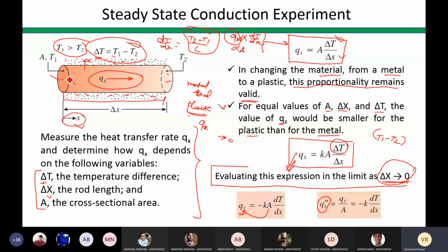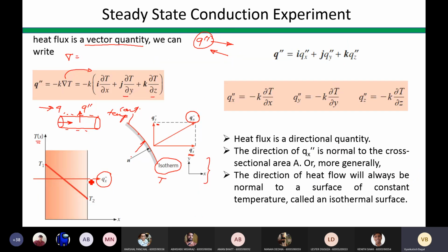Okay, here the area normal to the direction of heat flow is this face area, this one, correct? So conduction is taking place in this direction, right? Are you getting my point or not? And before this, there was convection taking place through the peripheral surface. That's why we took area as pi dl, and it is not pi dl here. It is pi by 4 d square for this case. I hope you understood this. Yes, sir. Understood.